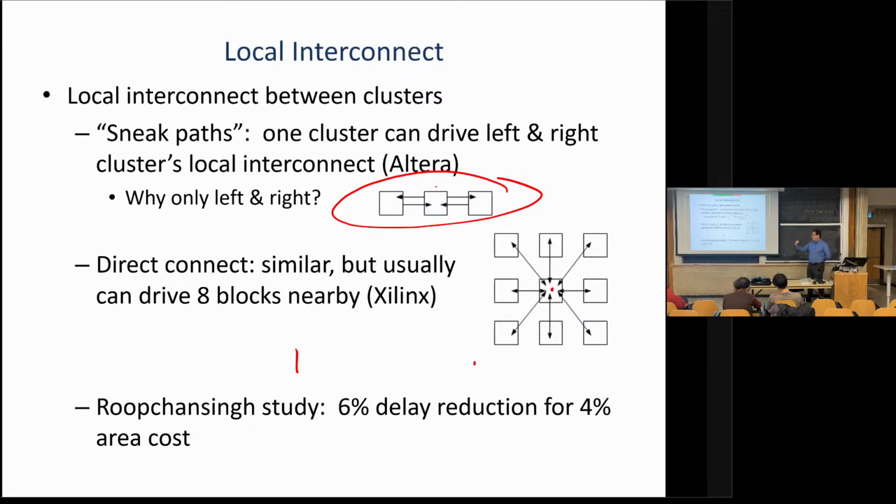area intensive than horizontal wiring, you'll notice that Intel architectures also have wider horizontal channels than vertical, because you can actually tell the CAD tools, to a reasonable degree, if you tell the CAD tools they have more horizontal routing than vertical wiring, it can change the placement to be biased towards horizontal wiring. So Intel does that. They actually prefer to make more horizontal wiring than vertical.